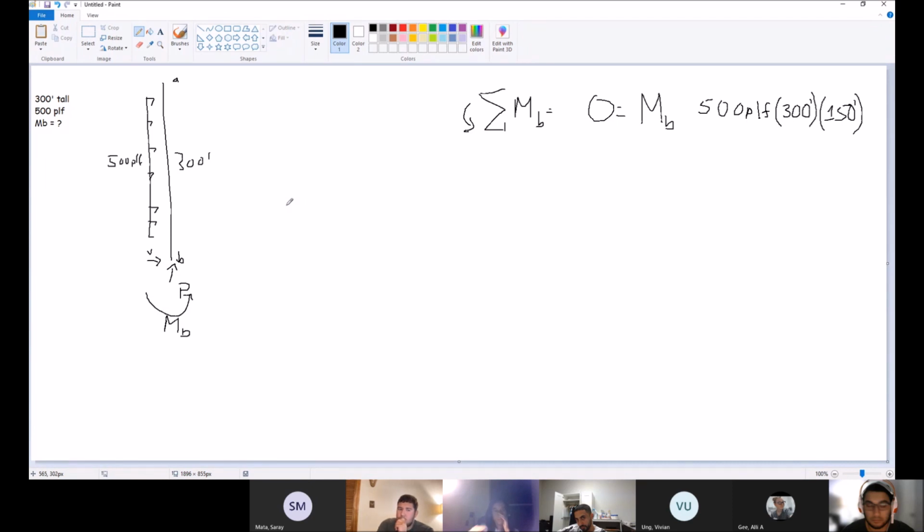So it's around point B. If that line load is going downwards, that's clockwise, negative. Remember, when we consolidate down to one point, one force is pointing in this direction, and then it goes clockwise around this point. Yes, that is negative. So MB is equal to positive all this, because we just moved this to the other side.